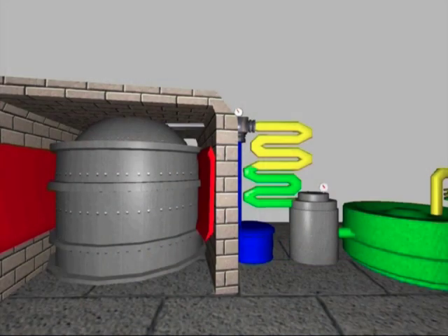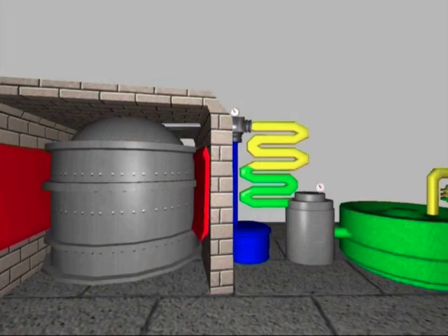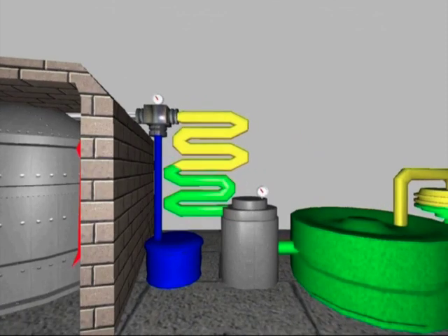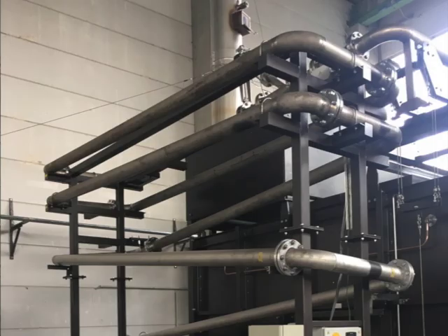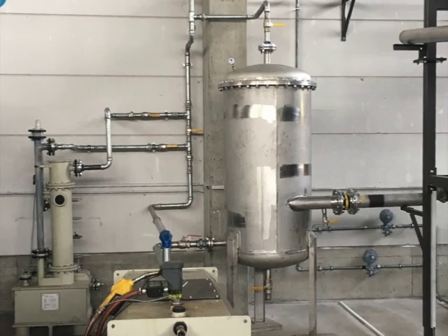When the necessary temperature has been reached, the materials within the reactor are gasified. The gas is then conducted through the connected tubes into the cooling system, and from there into the pressure reducing system where it condenses, to finally reach the provided storage basin as oil. Resulting condensation water will be let off previously into a collecting basin.